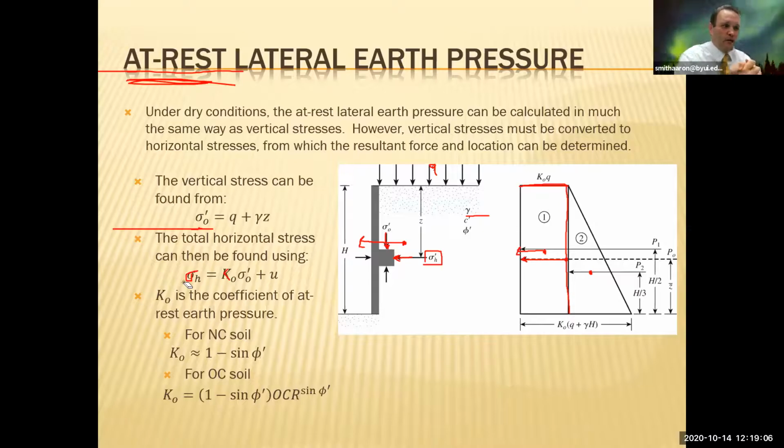However, if there's a water table, you also have to put in the pressure of your water. You can imagine if you were a wall on a swimming pool, the water in your swimming pool is pushing on that wall. So if you have a water table, you have to calculate how much water you have, the depth of the water times the unit weight of the water. That's another force acting on your wall in the horizontal plane, which is a little bit different. Before we were able to ignore this, but now we no longer can.